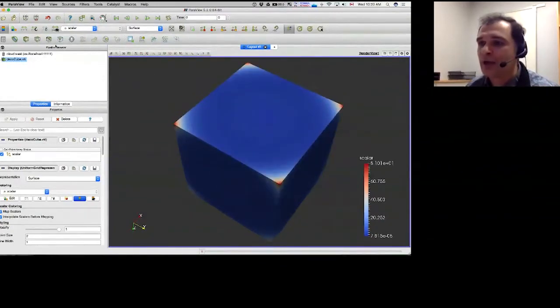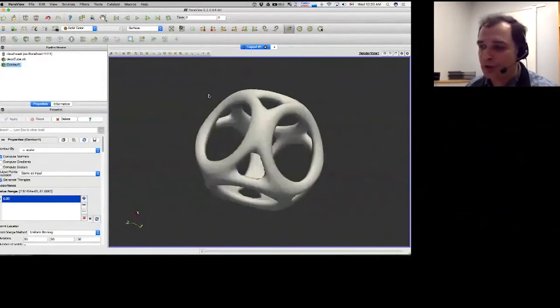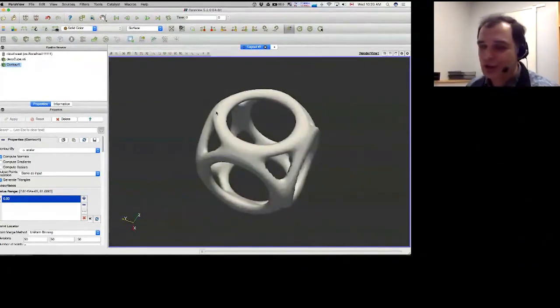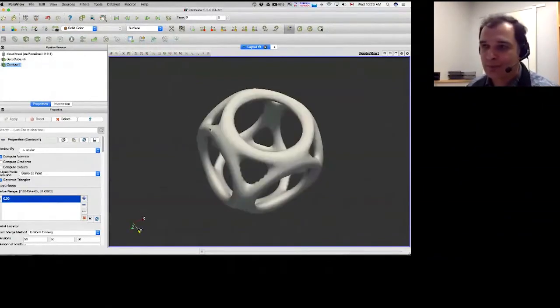All right, I'm going to call the contour or isosurface filter, and I'm going to draw an isosurface at the value of the function equal to 0.03. So I hit the apply button, and this is the visualization we'll be doing throughout today's webinar. Here we're doing visualization using the ParaView client-server connection. I'm running the ParaView server on the remote VM, and I'm running a ParaView client on my laptop. Most rendering is done by OpenGL on my laptop's graphics card. Really fast, really interactive, very smooth.